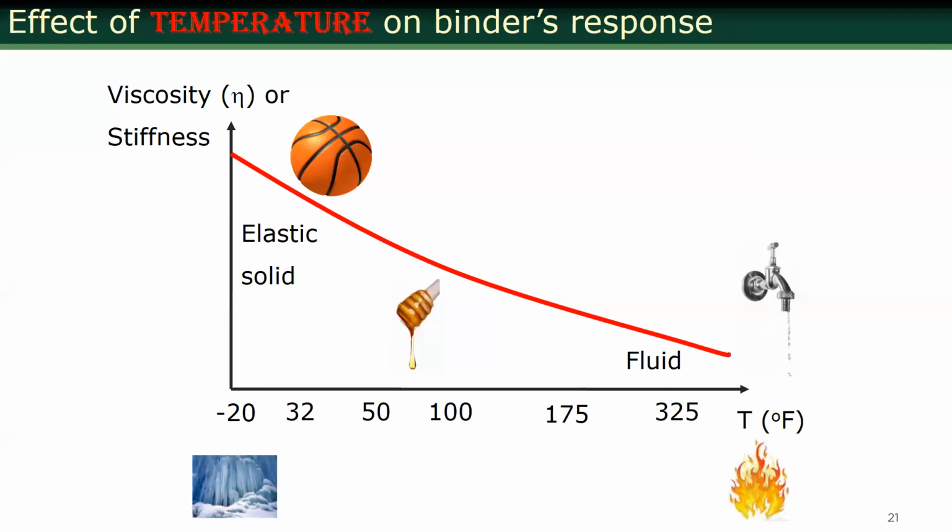Now, I'm going to talk about viscosity in a minute. Let's talk about stiffness and viscosity. I'm sure you know what stiffness means. So stiffness goes down, and viscosity and stiffness are related directly. Stiffness divided by frequency of loading is viscosity. They are the same thing. So as the temperature goes up, the binder becomes like honey, and as we go up further, it becomes like water. The viscosity becomes like water, and we want this.